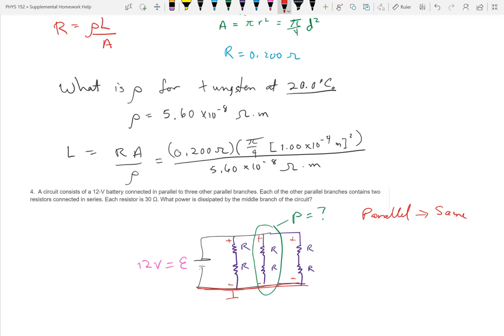I'm calling this 0. That means that in my head I put a ground connector there, so that's my reference. Sometimes we put it in a parenthesis, meaning it's not really connected to ground, but I'm considering it ground. And so these are all plus 12, so the voltage drop across each one of these is the same.